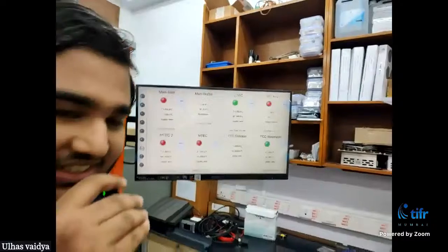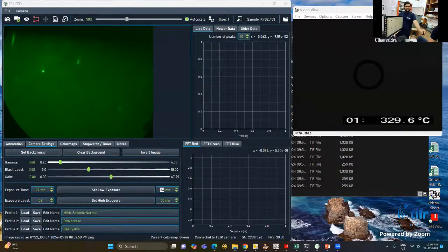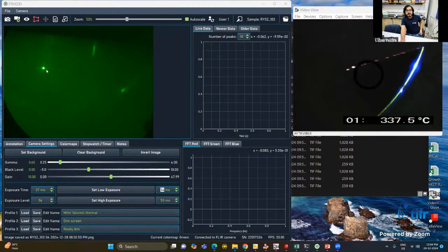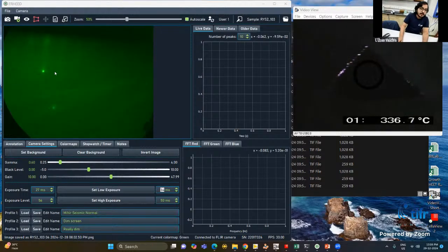Now you can look at the RHEED pattern and you will see what will happen. I'll just open the manipulator MBE shutter. Maybe show the RHEED. And yes, we are seeing the RHEED pattern of the gallium antimony. And similarly, like the other cells, we'll just open the manipulator shutter. Now we have opened the shutter, and I would like you to closely look at the RHEED pattern, and it will slowly change.